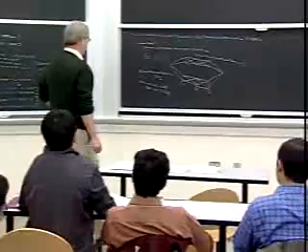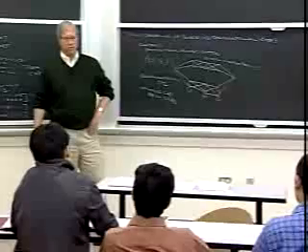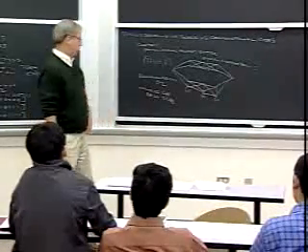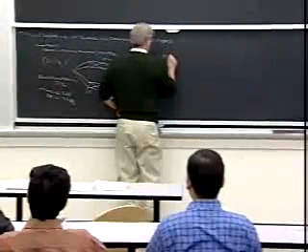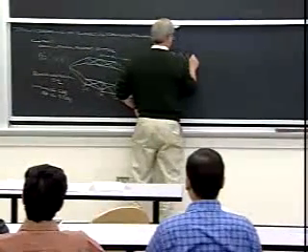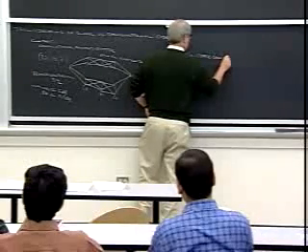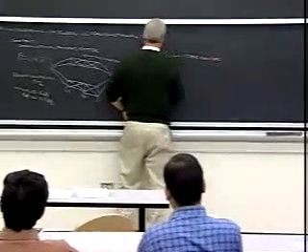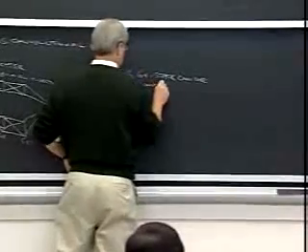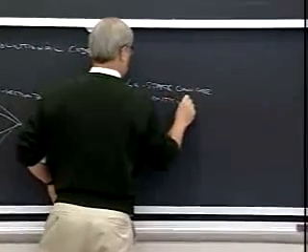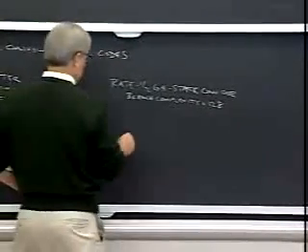And so this was their, they call it K equals 7, but in my terms, nu equals 6. 64-state rate 1/2 convolutional code. So let's take that. Rate 1/2, 64-state convolutional code, just with the standard trellis. So its branch complexity is 128 at every time, as a more regular structure than this guy.